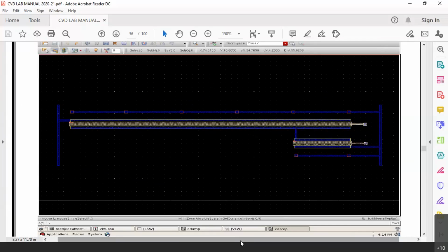Now you can see in the upper transistor, we have connected wires at the top with the metal line. Both NMOS FETs are in the P substrate. Around the transistor itself, the black screen is the substrate. The body of the NMOS FET is the substrate itself. The substrate needs to be connected to VSS because both are NMOS FETs. And every 10 micrometer, we should place one wire so as to avoid the leakage charges or the leakage current.